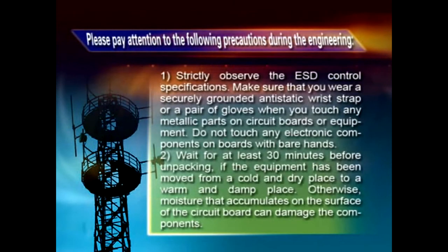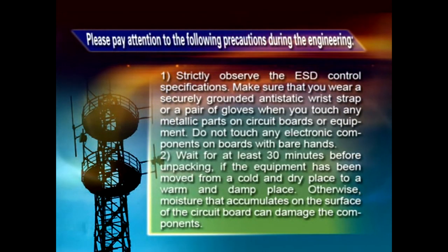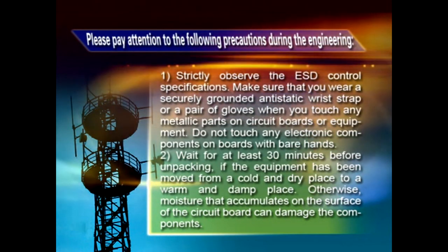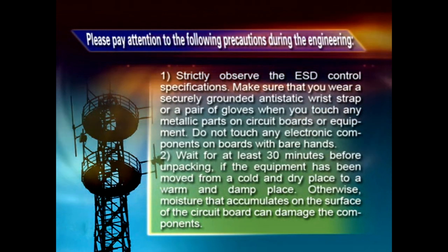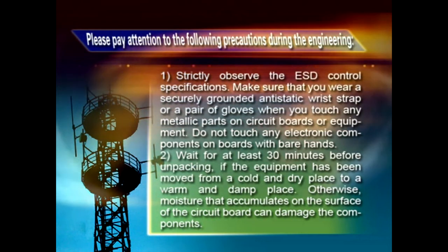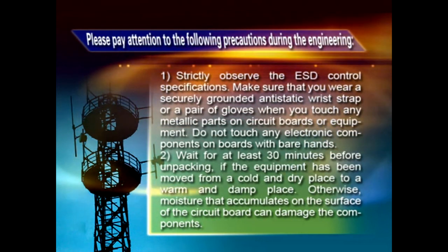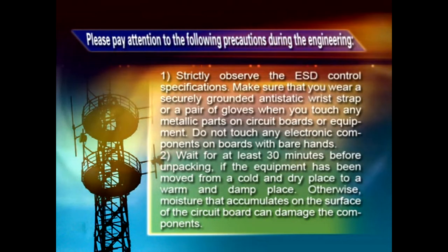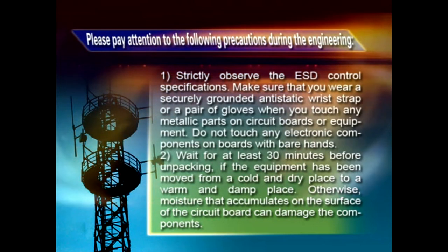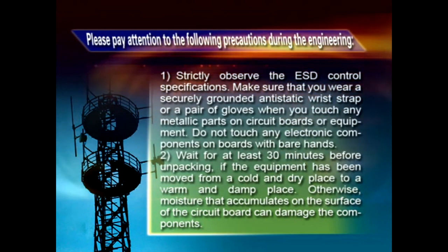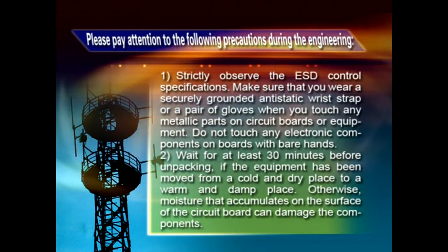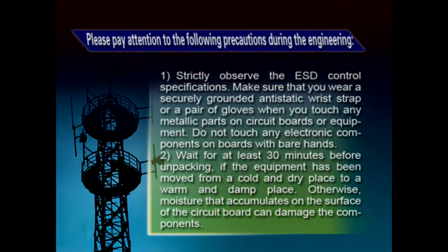Please pay attention to the following precautions during the engineering. 1. Strictly observe the ESD control specifications. Make sure that you wear a securely grounded anti-static wrist strap or a pair of gloves when you touch any metallic parts on circuit boards or equipment. Do not touch any electronic components on boards with bare hands. 2. Wait for at least 30 minutes before unpacking if the equipment has been moved from a cold and dry place to a warm and damp place. Otherwise, moisture that accumulates on the surface of the circuit board can damage the components.